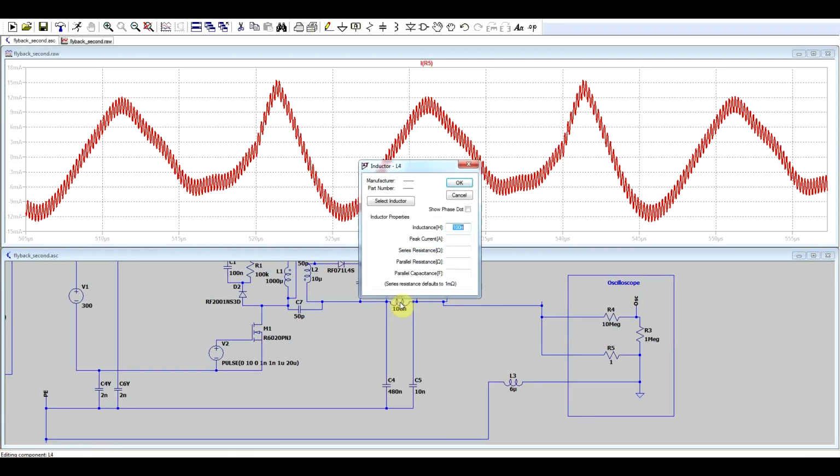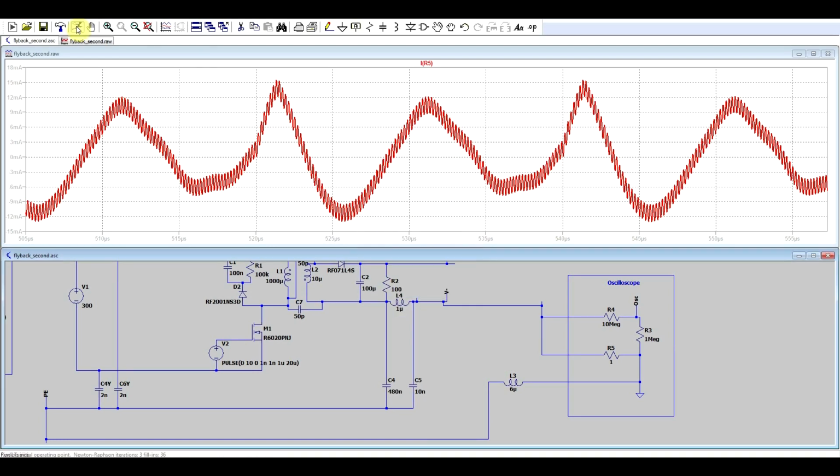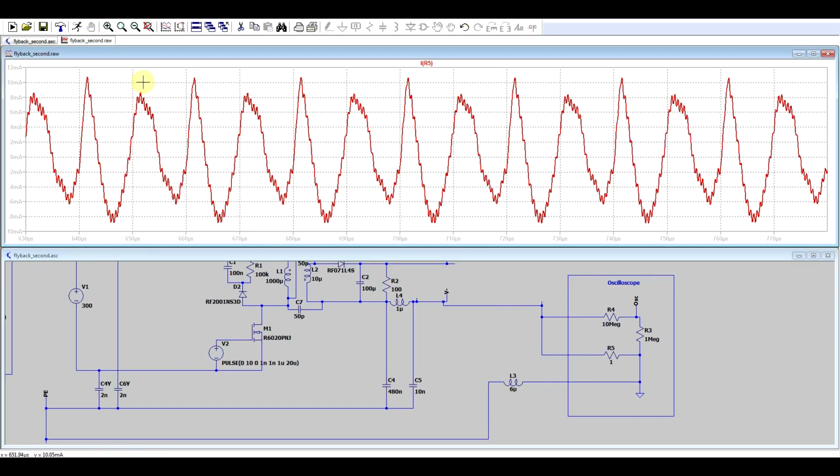Now another thing we can try at this point is work on this inductance. If we had a larger inductance and resimulated this, we would notice that the current is going down. So we're building a better and better filter, the higher this inductance is. At the moment, this inductor is only formed from the wiring existing between the power supply board and the output connector. Now you could add inductors in here, but they would need to be rated at 5 amps at least. And that's not a very cheap inductor.